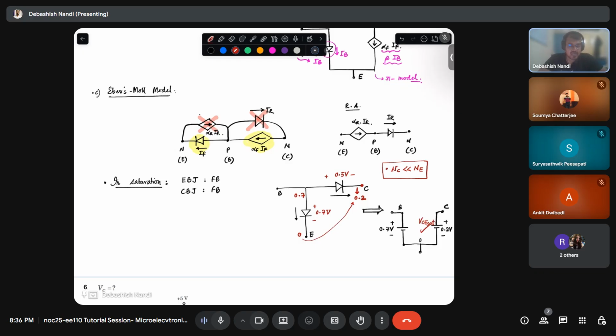And that is why in case of silicon, you take it as VCEsat. So for common emitter configurations, the quick way to check if your device is in saturation is to see your VCE terminal. That means you don't need to always check the collector to base voltage, because it is difficult for us. Why? Because this is my common terminal, right? So this will be my input side, this will be my output side. So it will be easier for me to probe these points. So this is my VCE. If this is greater than VCEsat, I can infer that my device is in forward active. Fine.